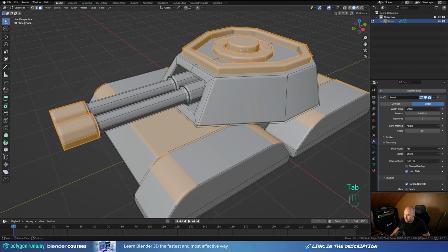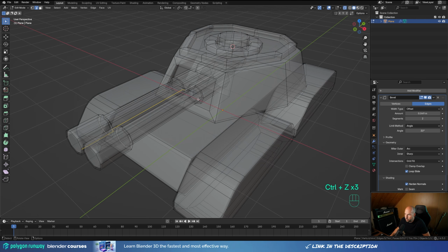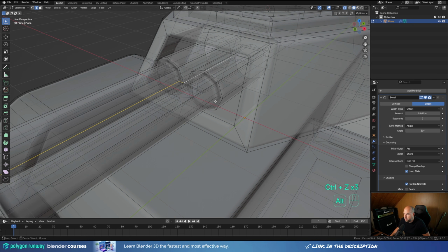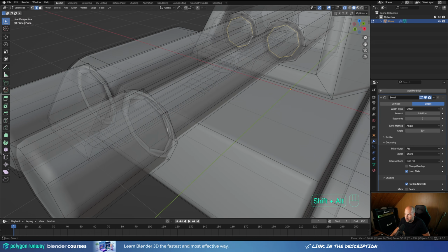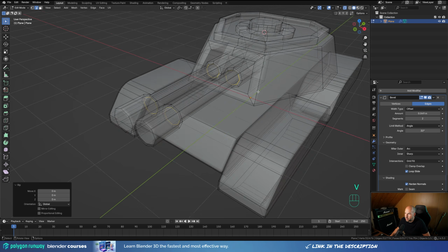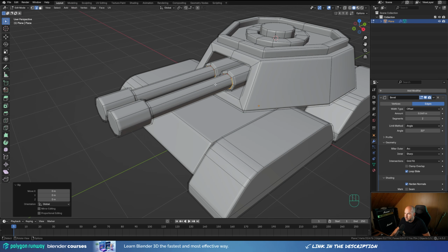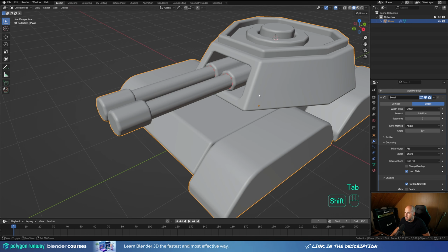So if you go into the edit mode and enable X-ray view, you can press 2 for edge select or click here. Let's hold Alt key and select this loop on the Canon, hold Alt and Shift and select another one, and right here as well, and here. And now we'll press V to separate this and right click to release. And now if you toggle the X-ray, you will see this is no longer connected, so the bevel modifier doesn't kick in there, so we can tab out.